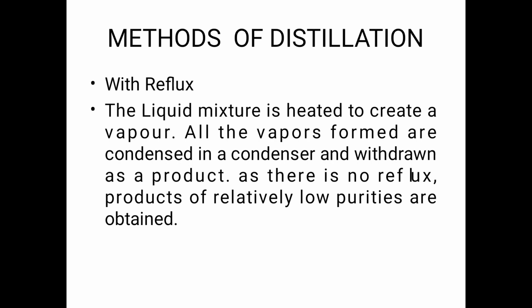With reflux means one part of the distillate is again sent back to the distillation column. What will happen? Again, more contact of gas and liquid phases, the mass transfer rate is high. At that time the separation efficiency also increases, and the product purity may be increased. Without reflux is mostly used only for laboratory purposes.